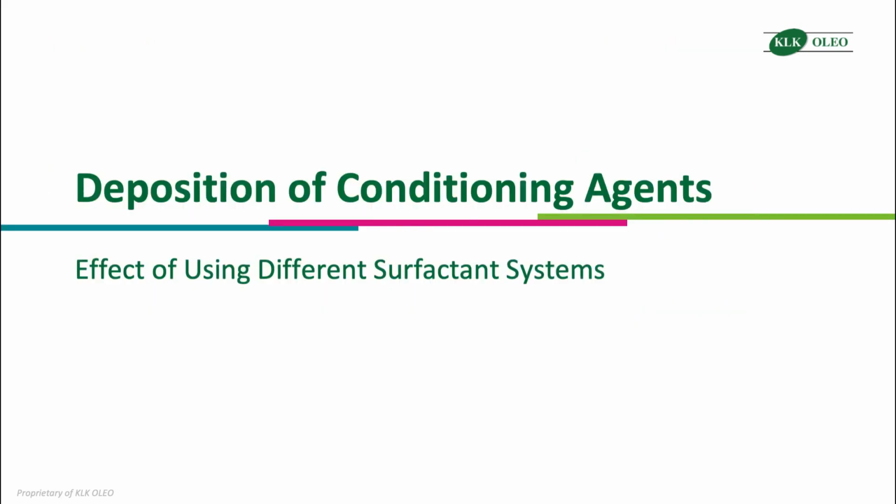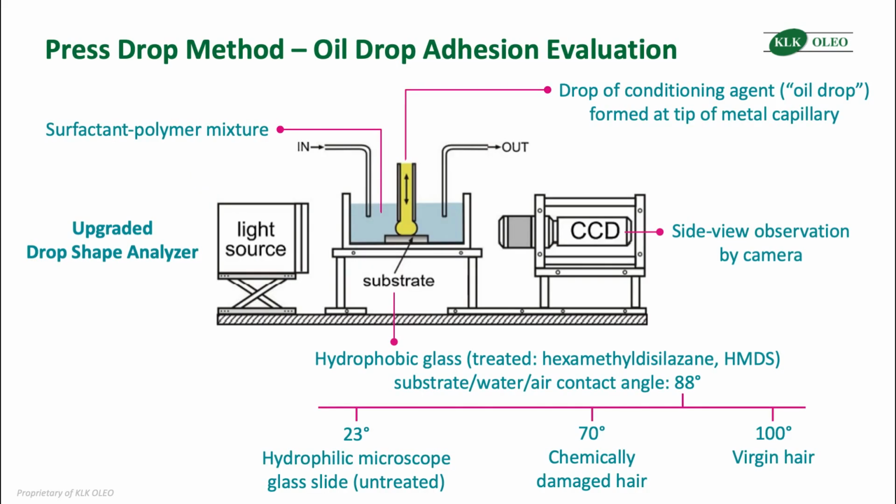We were interested to compare the effect of using different surfactant systems on the amount of conditioning agents deposited. To conduct this study, we used the pressed drop method, which evaluates the adhesion of an oil drop to a substrate. A drop shape analyzer was upgraded with a piezo-driven membrane for precise control of the oil drop volume. A drop of the conditioning agent, which we will call the oil drop, was formed at the tip of a metal capillary that was submerged in a surfactant and polymer mixture.